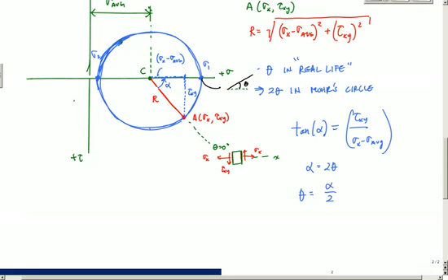And then after I draw those lines, I'm going to draw a line perpendicular to that line, and this face right here essentially represents this point. And here I've got sigma 1 going that way at an angle theta, which is equal to alpha over 2. So this is sigma 1, and that'll be the state of stress.